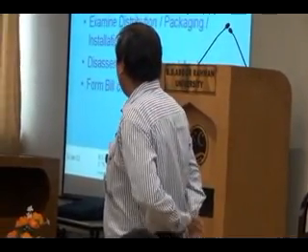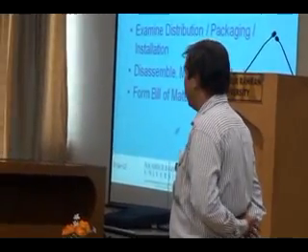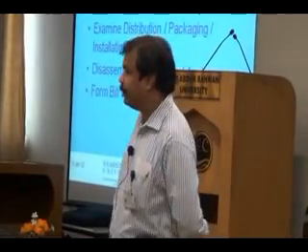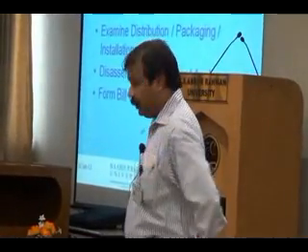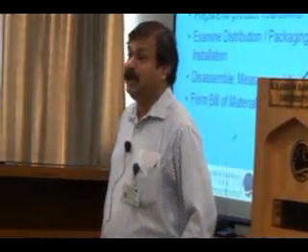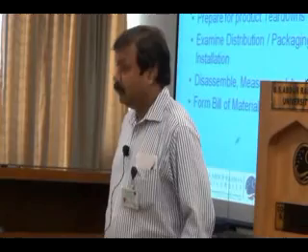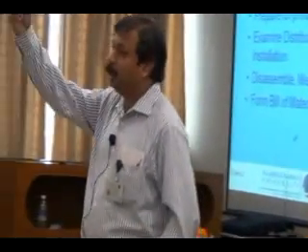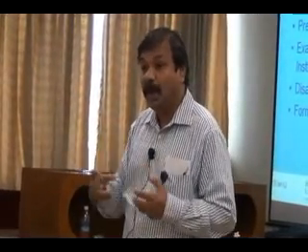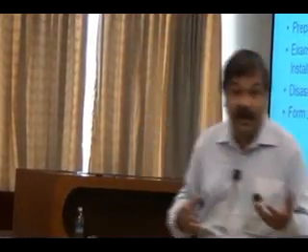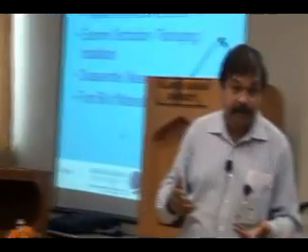Number 2, you have to prepare for product tear-down. There are many preparations that are required. For example, what are all the things that you want to measure? When you do the tear-down analysis, depending on the objective, if the objective is reverse engineering, then I may have to measure all the dimensions of individual components and then probably generate a design itself.